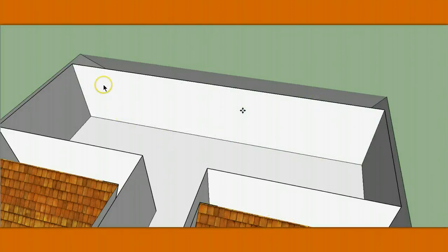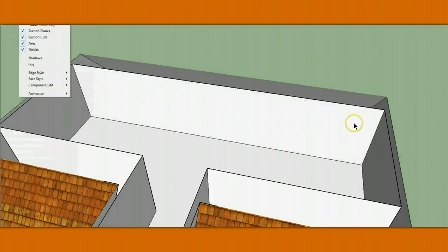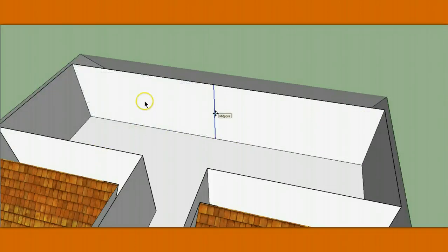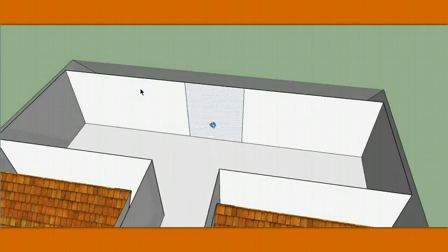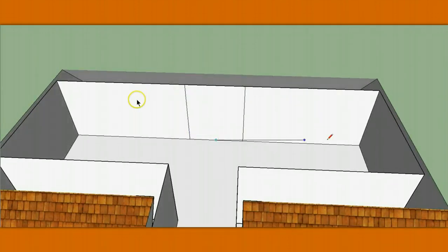Of course, now this is an interior wall which doesn't exist in your home upstairs at all, but we would create a smaller wall deeper into the roof line, and I called it a pony wall, which would be something like this, instead of the full wall. And then you'd have your beams coming up and exposed beams, and we'd put the sheetrock in there, as I referred to, and make it real nice, and give you that little reveal of maybe a couple of inches of your nice 2x4 rough sawn beam.